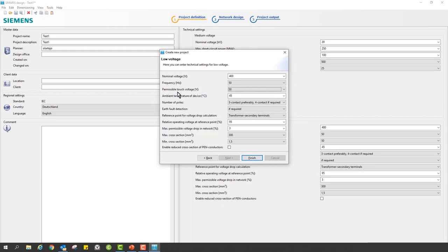And there are some, let's say, critical things that we need to understand and get to know why they're here. The permissible touch voltage is one of these critical things. This is based on the safety to touch when something might be energized without us wanting it to be. 60204, the safety standard for electrical machinery equipment, bases its calculations on the skin and health of the user.